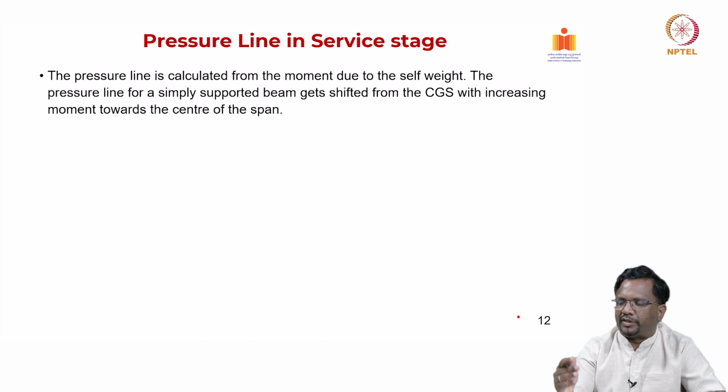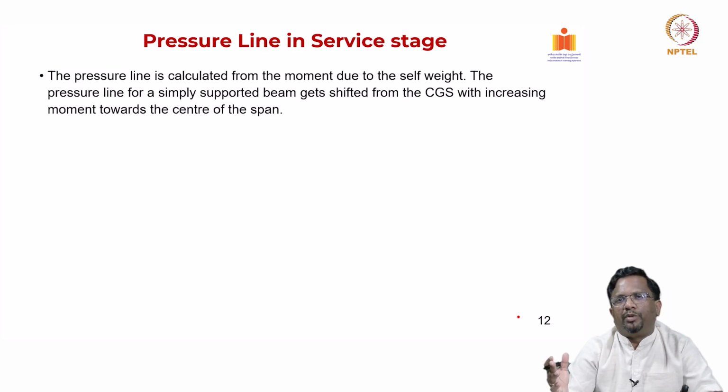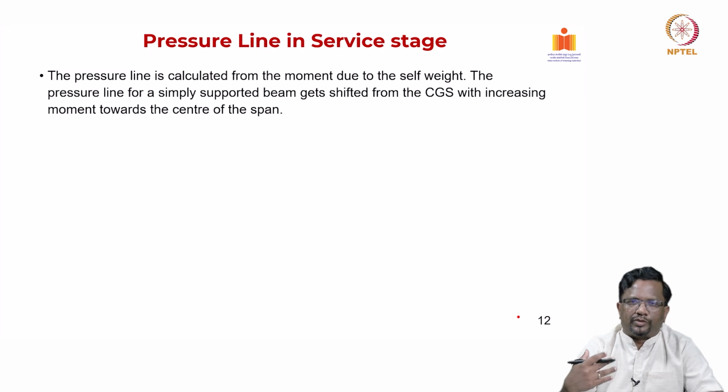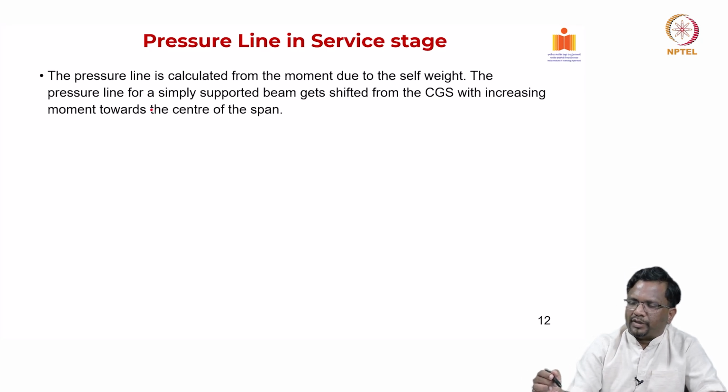Now, at service stage, this is transfer. What is the difference between transfer and service? At transfer, only self weight will be acting, and there are not going to be much losses, but in service, there will be a drop in pre-stress also. We have studied that in the losses section, so we have to calculate that.